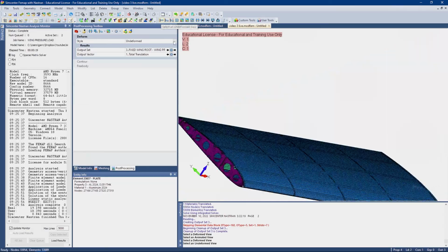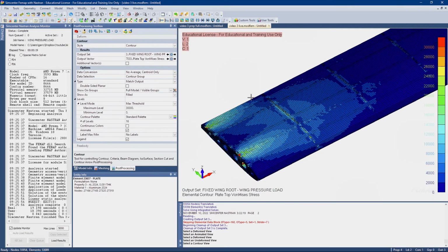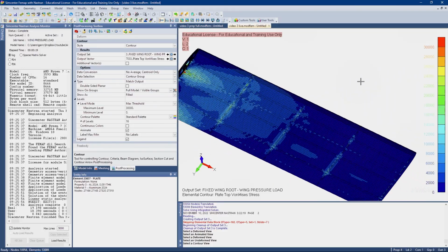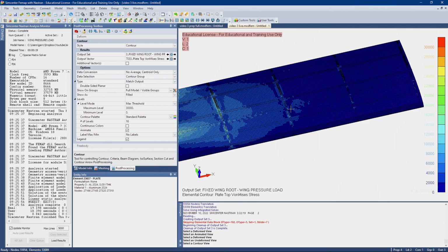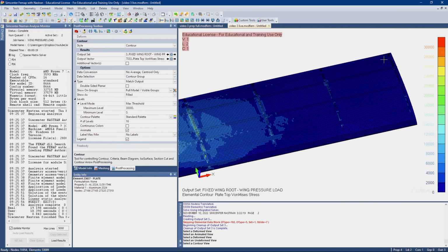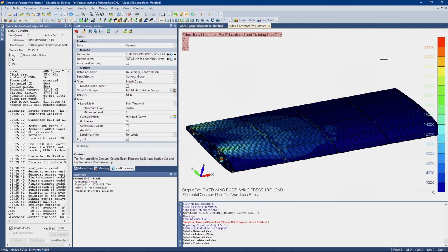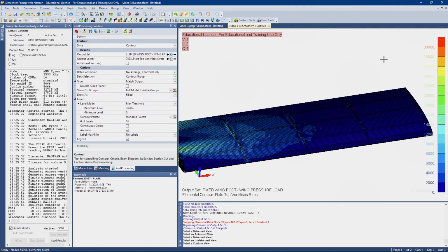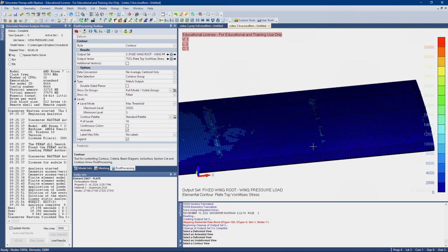Let's now check out our von Mises stress. So we have it set to 30,000 here. The skin looks good. If we wanted to, we could potentially even go thinner. In reality, this would be a couple panels, different panel sizes and whatnot. We've just modeled it as one big skin, which is not a terrible approximation. It'll be a little bit of extra stiffness, but not terribly wrong. But we'll have different panel sizes, so we could probably even go a little bit thinner down here.